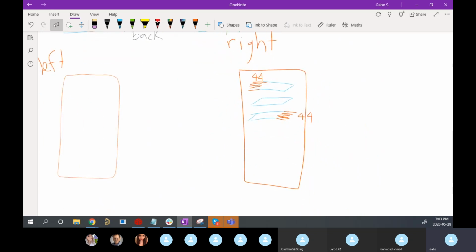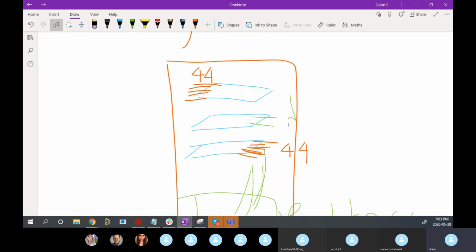So batteries. So this is nice, right? The bottom board measures all the temperatures of this battery nice and close together. Then the ADC talks digitally, right, digital to the BMS master, which is the same box. Digital to BMS master.